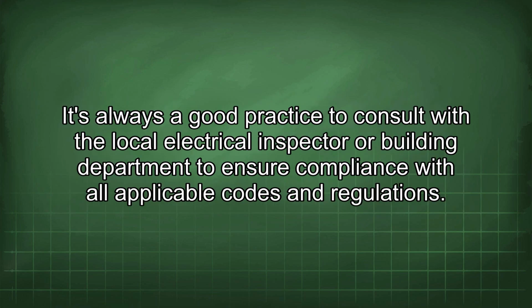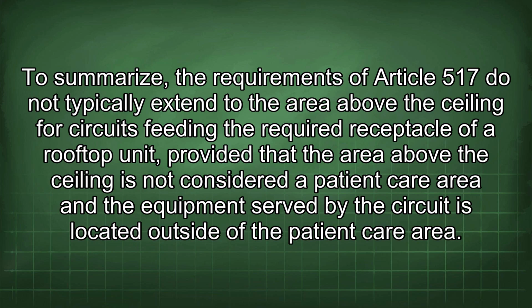It's always a good practice to consult with the local electrical inspector or building department to ensure compliance with all applicable codes and regulations. To summarize, the requirements of Article 517 do not typically extend to the area above the ceiling for circuits feeding the required receptacle of a rooftop unit, provided that the area above the ceiling is not considered a patient care area and the equipment served by the circuit is located outside of the patient care area.